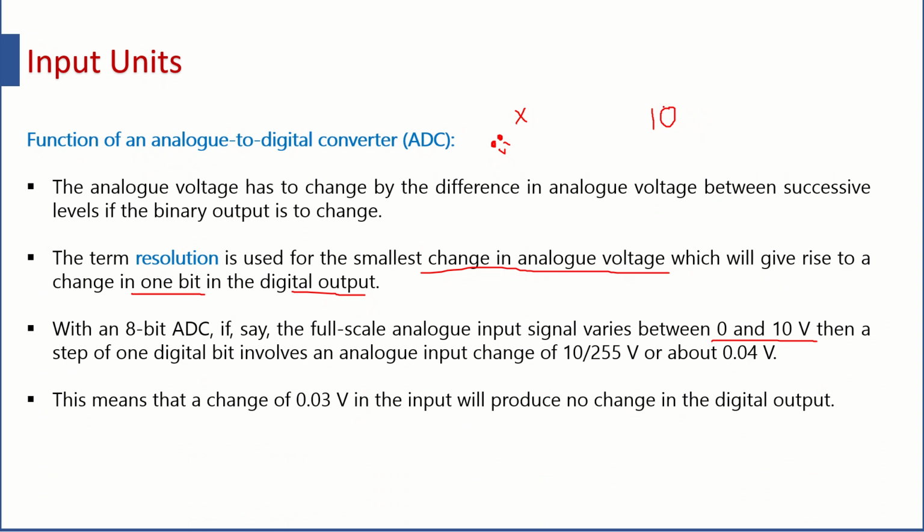तो वहां पे there is a particular pin called reference pin. तो रेफरेंस पिन में आपने अगर 10 वोल्ट दिया and here कितने बिट हैं आपके पास? You have actually 255 steps because 2 to the power 8 is equal to 256. 0 to 256, 255 होता है. सो टोटल 255 होता है. तो यहां पे आपका वैल्यू आता है 0.04 वोल्ट.